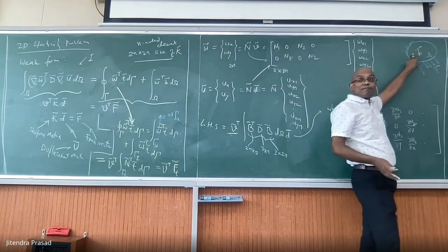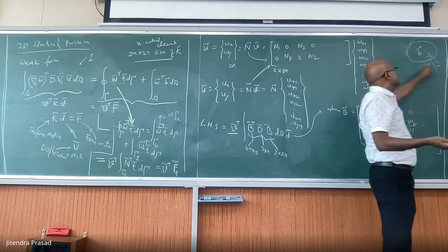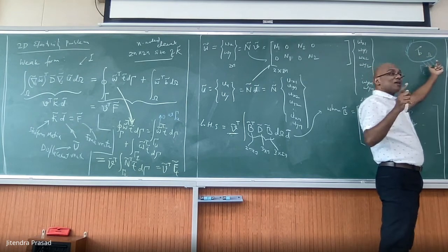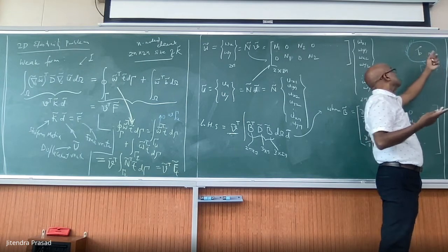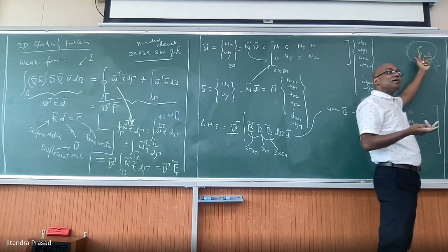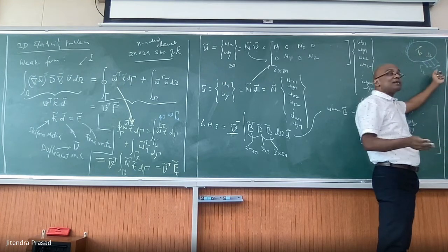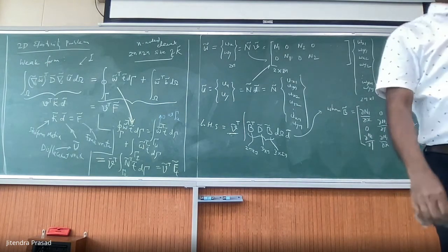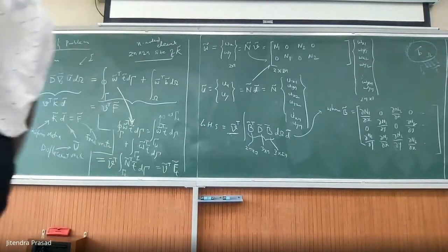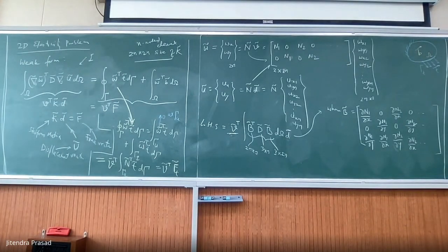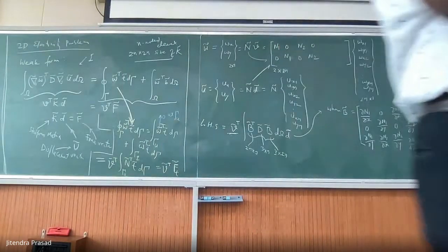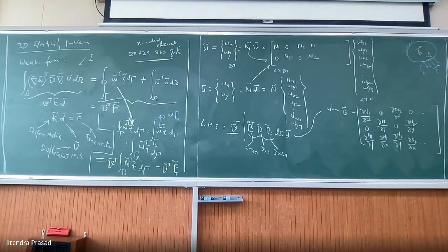It is same as in the heat transfer problem. You have a heat loss at the surface. So the force vector will also have to take care of that. A force vector will also have the heat generated. So B here is a kind of heat generation. T here is like a heat loss. Again here, since it is not about energy, there is no loss kind of thing. This force is force. So you don't say that there is some kind of loss here. It's just the gradient, a flux. So ultimately we're talking about the flux.